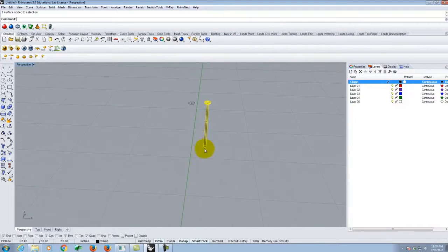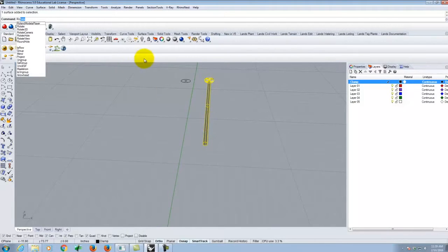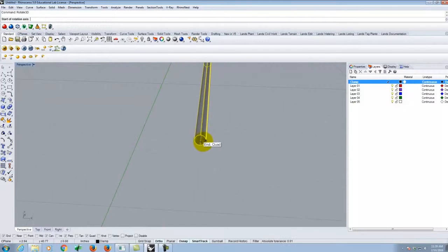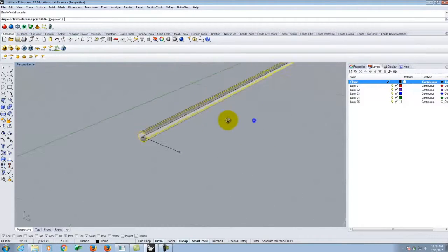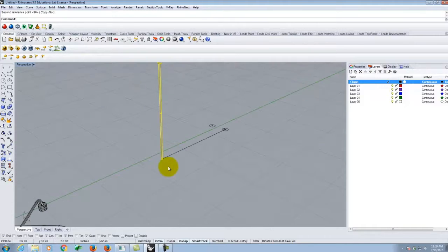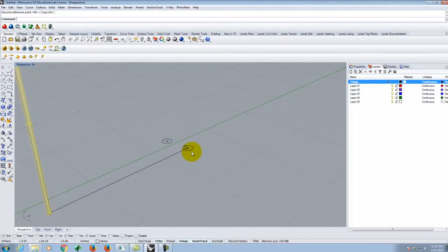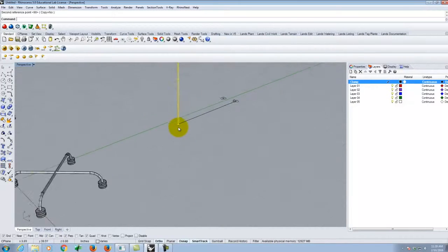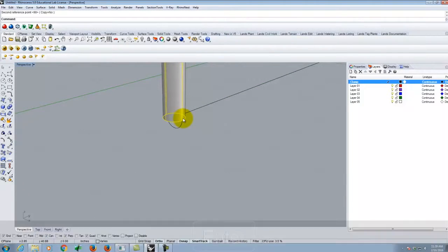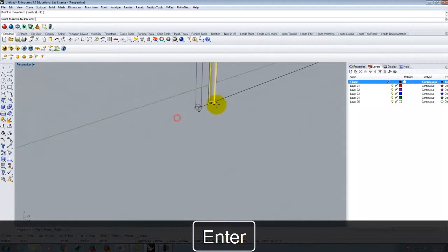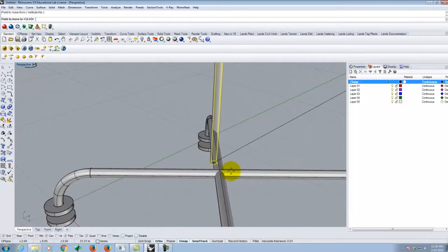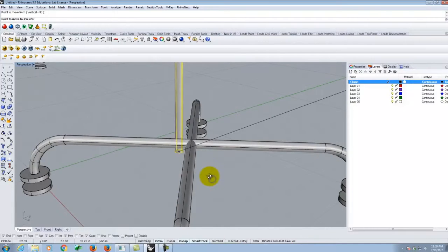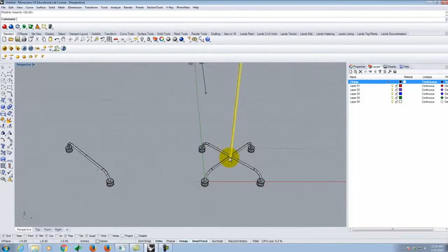I can go ahead and do a rotate 3D while I'm in position here. Rotate 3D. And we'll go from the bottom there, and we'll fold it up into the third dimension. I've left my curves behind. It doesn't make any difference at this point because I already have the geometry that I want. And then from here, I can go ahead and move from there to right. Come on. Let me make sure midpoint is on. There it is, midpoint. And now that comes, and those two connect together.